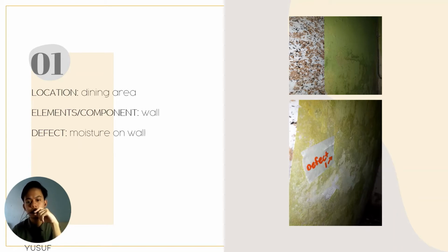The remedy is basically to drill a hole at the moist area and break the wall to see the broken pipelines clearly. Cut away the broken pipelines and replace them with new pipelines.